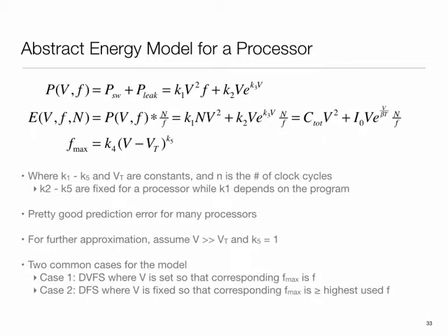Okay, so fair point. Generated heat in terms of joules is certainly a function of those. It's just that oftentimes we care about the rate at which the heat is generated, because my cooling system would have limits on it. Okay, so what would happen is if I'm generating more heat than what my fan or cooling system can remove, then the temperature will go up and then bad things will happen. So given any system, there is usually a limit on the rate at which you can generate the heat.